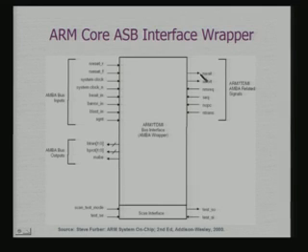Similarly, you have the sequence signal. We have seen how this can be used for accessing DRAM in a burst mode, where I can get data from consecutive locations after selecting a row. This is used in defining what kind of transaction is actually taking place.